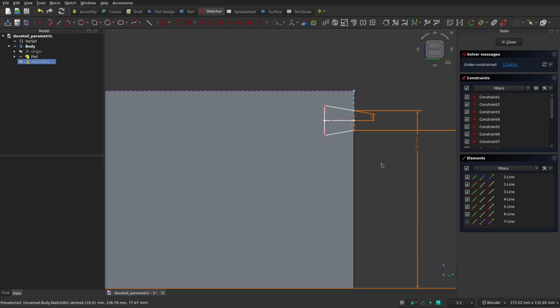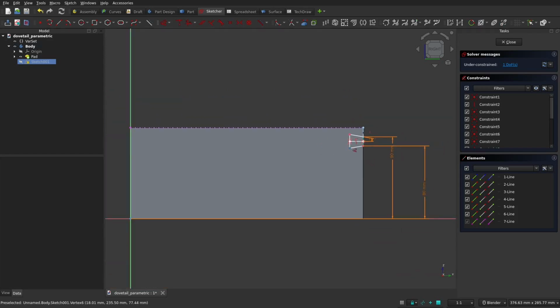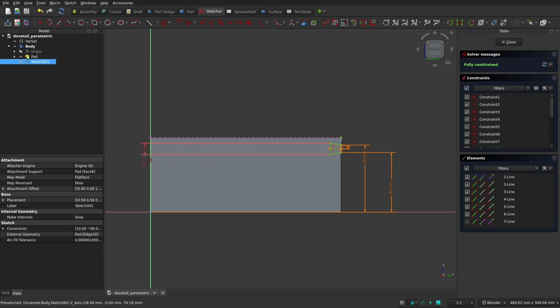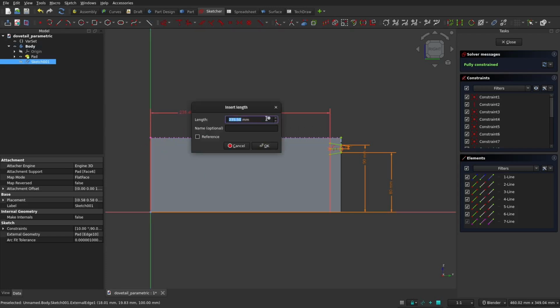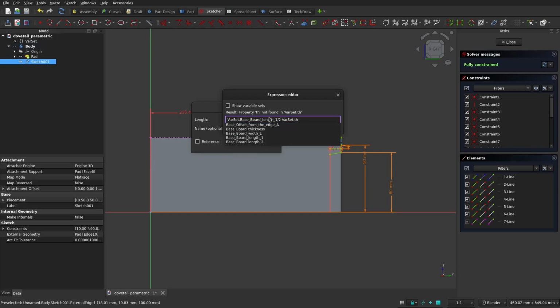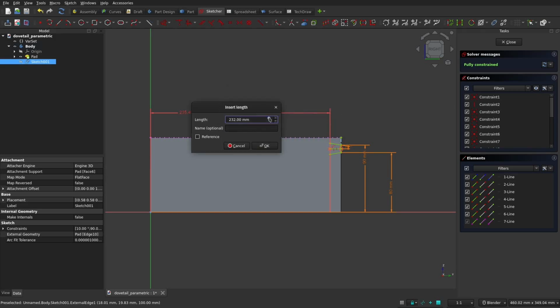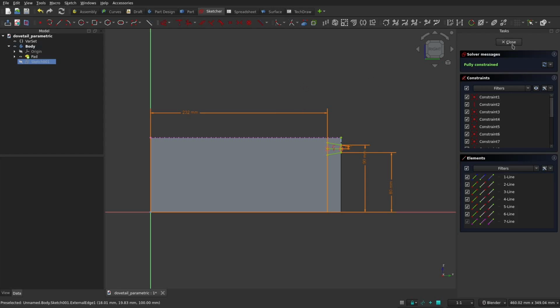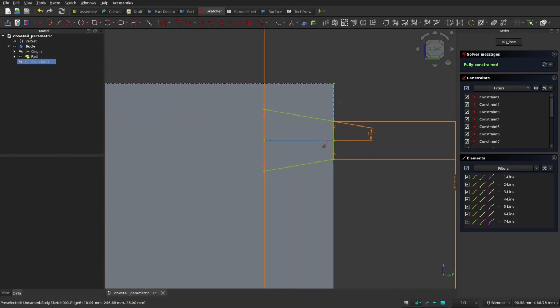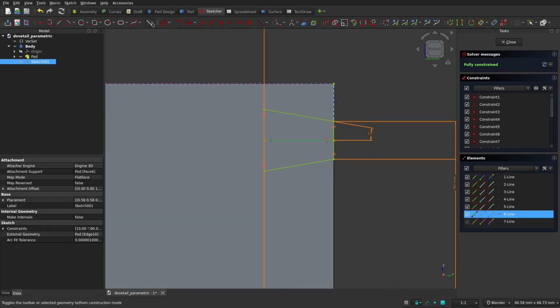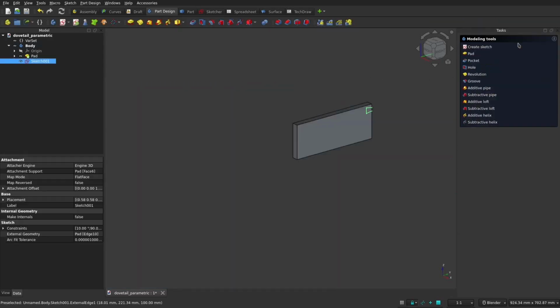We will now define the socket depth. It corresponds to the board thickness. We will define it from the origin, so the value must be equal to the board_length_1 variable divided by 2 minus the board thickness. Before closing the sketch, be sure to convert the dovetail symmetry line into a construction line. Generate a through-all pocket feature.